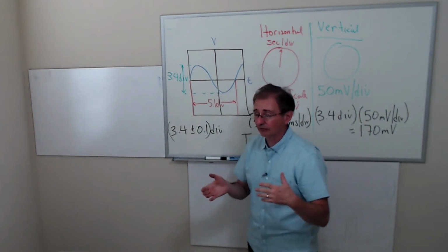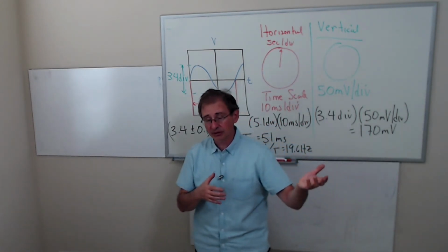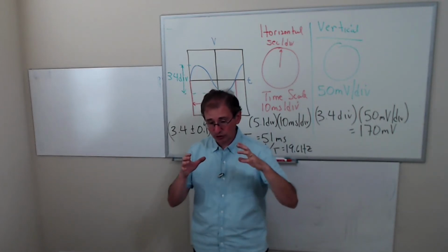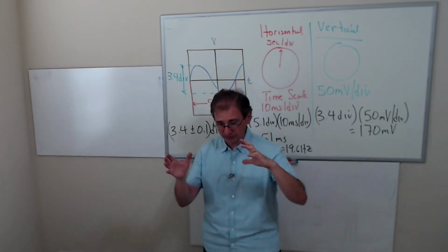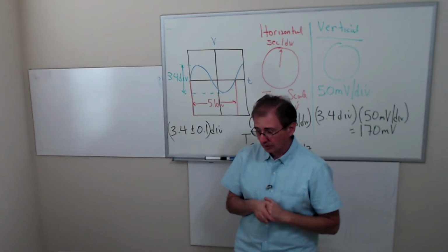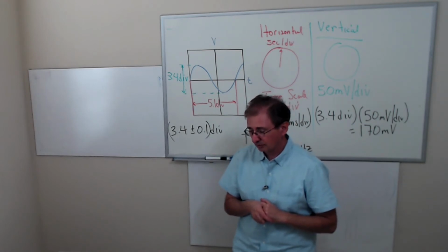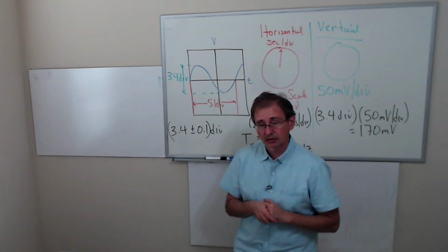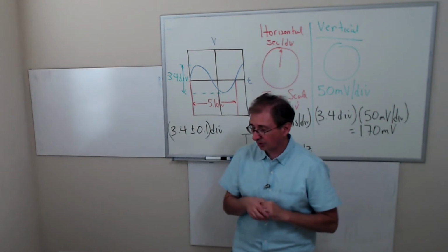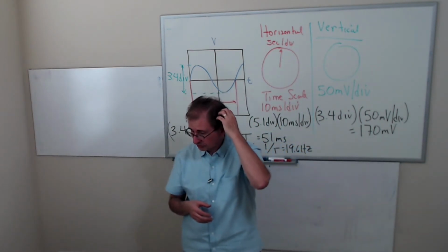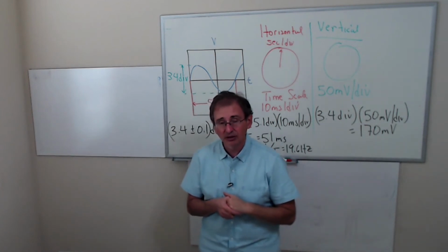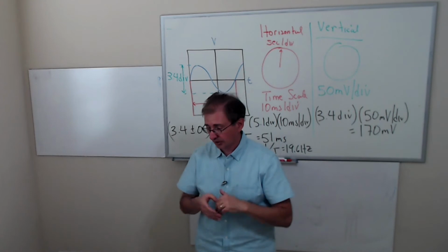And that works well if you're doing signals that are not very high frequency, and for the cases where you're just looking for a particular signal out of something complicated. It'll allow you to see that. For us, the auto will work fine because our signals are going to be clean. Generally, they'll be fine. But if you have trouble observing your signal, you can always use the normal one. And then there's a third mode called SINGL for single. Basically, it just takes one snapshot and that's it. You're done.